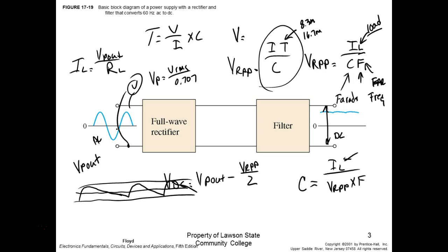The capacitor could be leaky, right? Or it could be open. If it opens, then it's going to be really low, because then you come from unfiltered back down to pulsating DC, right? You understand? So if you get a really low output, that's a good thing. Your capacitor could be open, or it could be leaky, which means it turns into a resistor instead of a good capacitor. So that's good. If it's slightly low, or not really, really low, then what could cause that to happen?